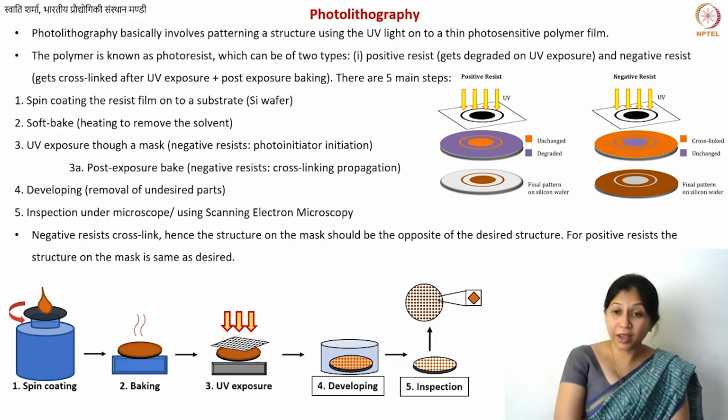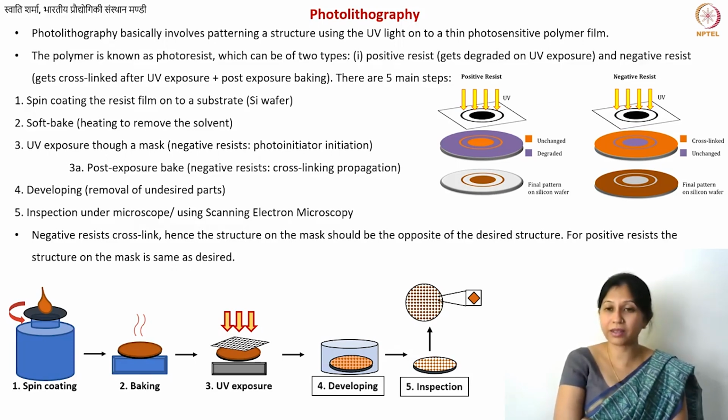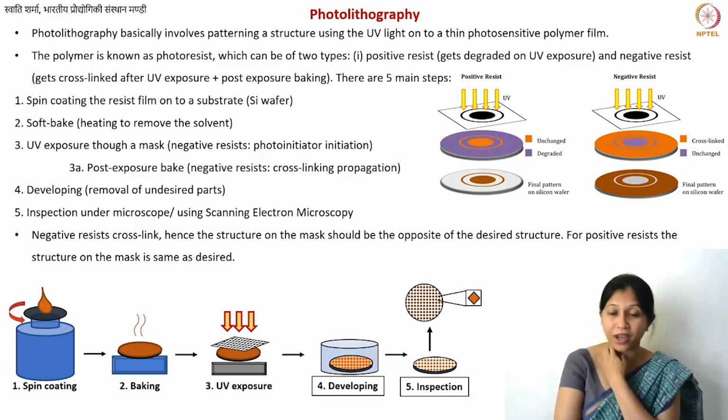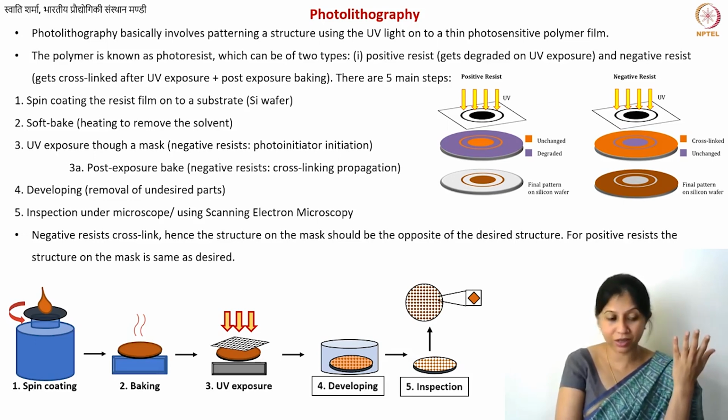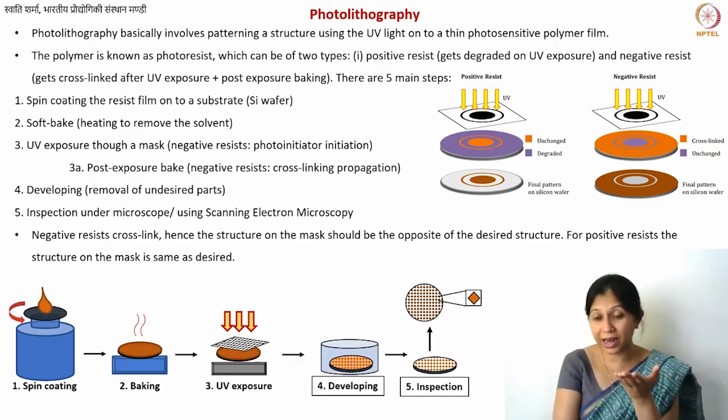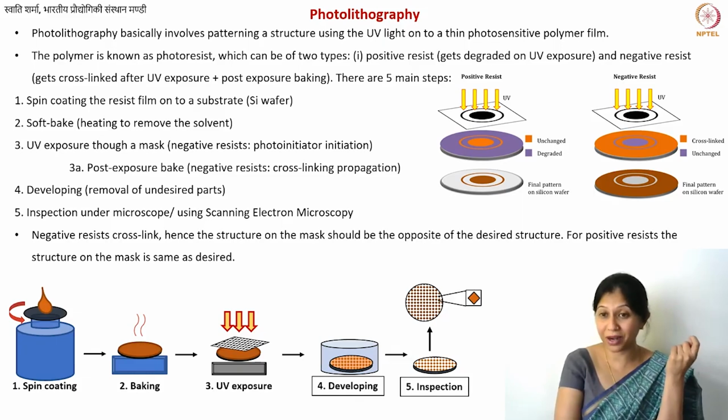Because when you're performing this heat treatment operation, you are heating it very slowly, at lower than 5 degrees centigrade per minute. That's your ramp rate. So this process goes on for several hours, and when you reach the highest pyrolysis or carbonization temperature, 900 for example, you would keep your material at 900 for at least an hour.